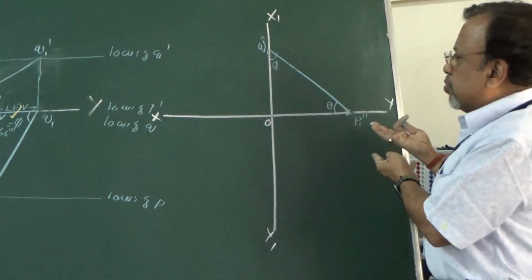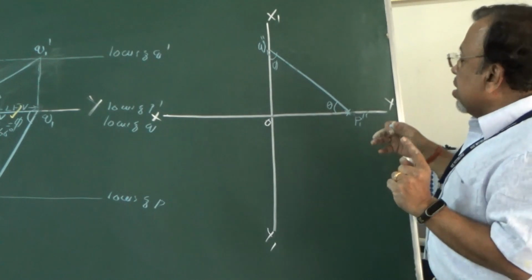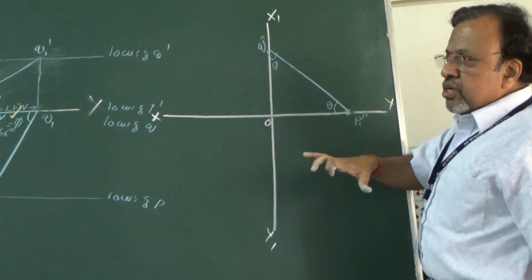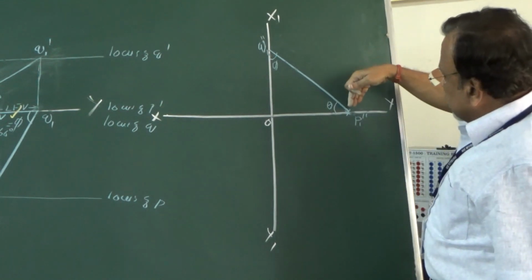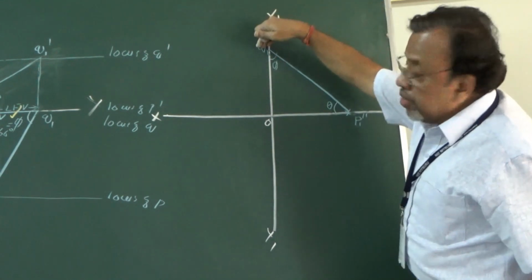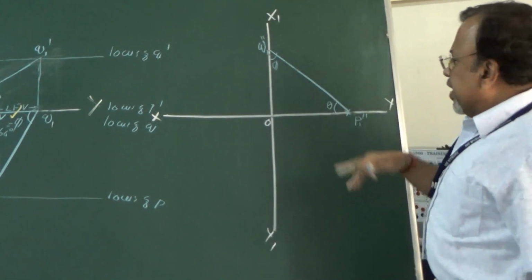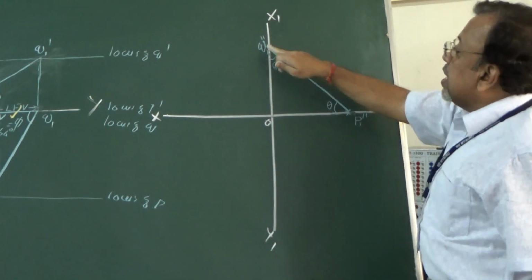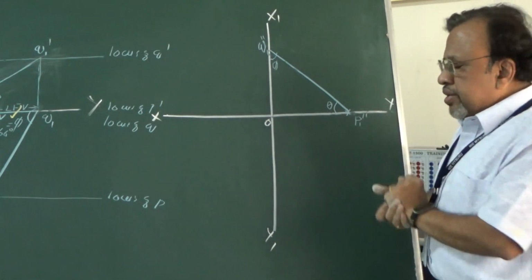Okay, but since I am doing it just like that, I am considering it here for 75. But strictly speaking, when you are doing it on the drawing sheet, you have to first get this 75 with this angle, and also since I know that P is in HP and Q is in VP, then I will draw this x1 y1 line, so that now I can say that P is in HP and Q is in VP. Okay, now I have just drawn the front, side view.